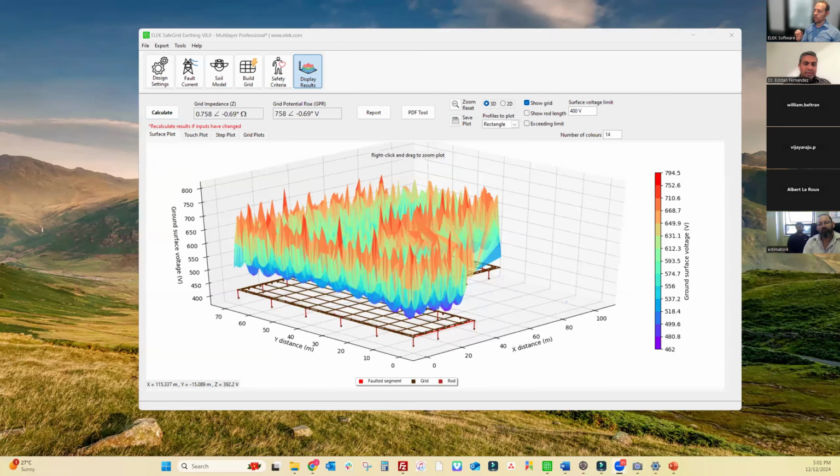However, generally when we're doing the design of a substation for a wind farm, we need to do the design in isolation of the wind farm first. So we can't 100% rely on the fact that the substation will be connected to the wind farm. But at the end of the day, it will be interconnected. So what we model, what we design will be conservative because it will be in isolation. And then afterwards, we will connect everything together and everything should perform even better.